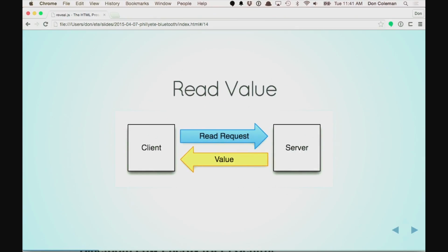So now here's where we get into attribute protocol. This is basically just the way that once the devices are connected, we can exchange information. These are going to be client-initiated actions. And you'll notice the names have changed. As we went from GAP to attribute protocol, it becomes client and server. So now in this case, the client is the phone, and the server is the light bulb.